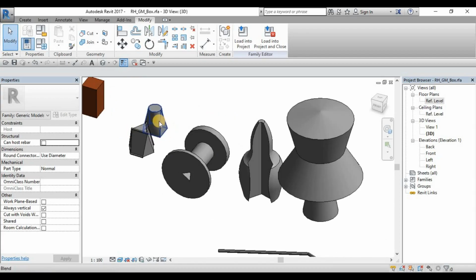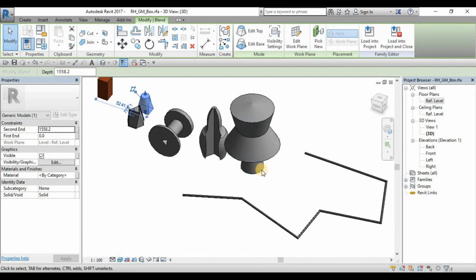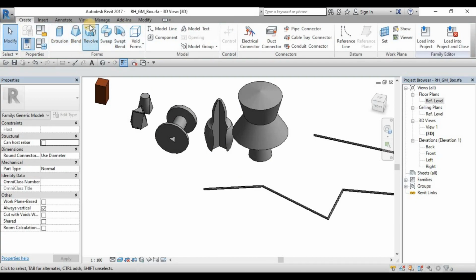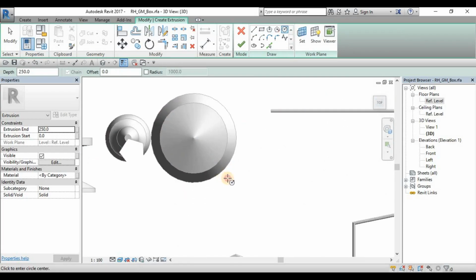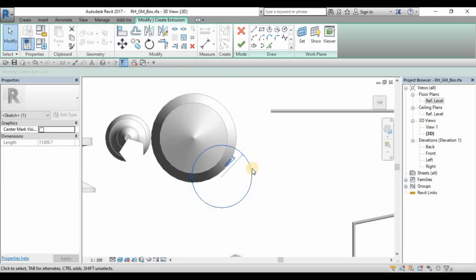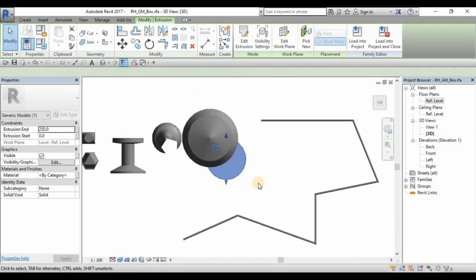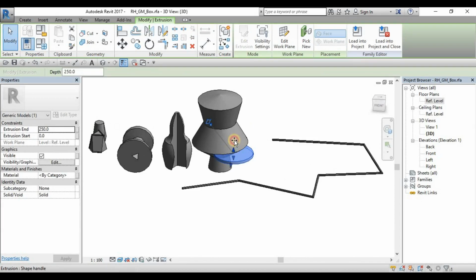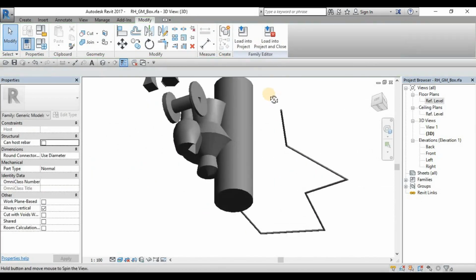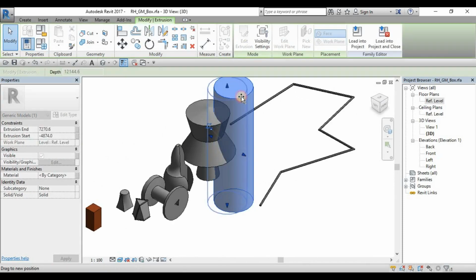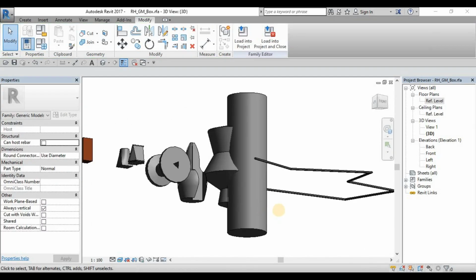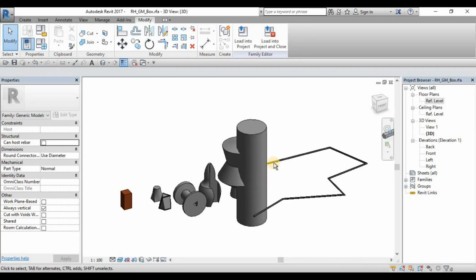But normally, for myself, when I do a void, I use the form command first. So I'll let you check how I do this. I'll command an extrusion. Let's say I'll do some circle void on this element here. What I would do is create a huge circle here that intersects the element, and then I'll just finish it, and from here I'll just drag it all throughout that element. So then I'll see first how it intersects my object. Then after carefully checking, if I'm not satisfied yet, I'll move it a bit. There you go. So yep, I'm satisfied with the intersecting polygon.